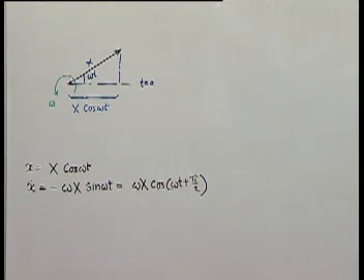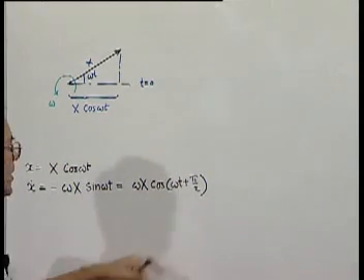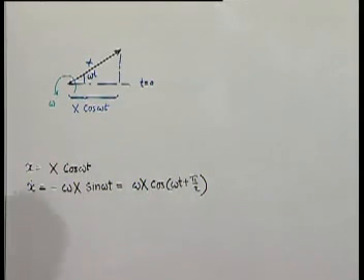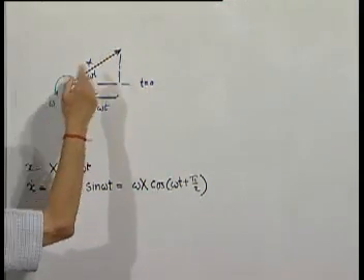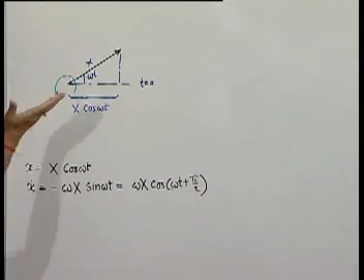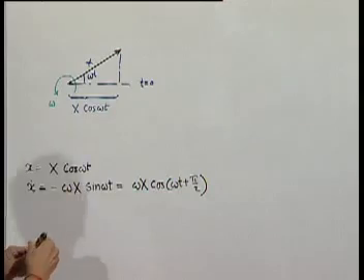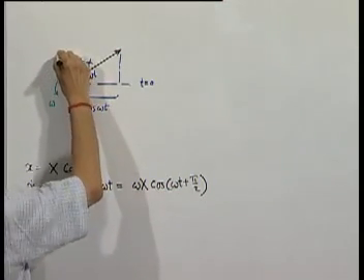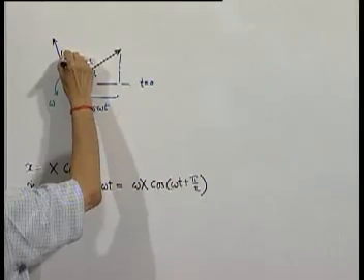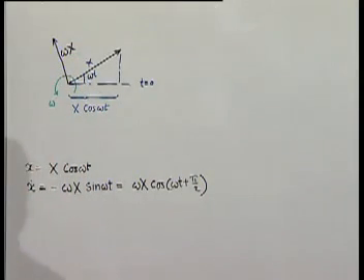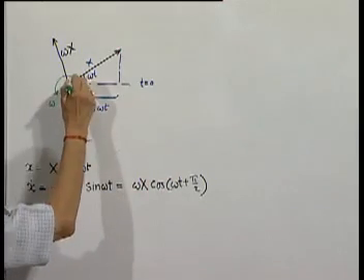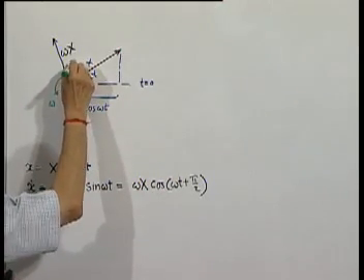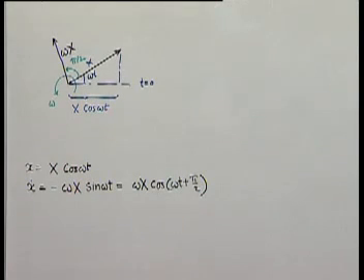So now it is again a harmonic function of time, whose magnitude is omega x, and it is leading the x vector, or the vector representing the position, by 90 degrees. So x dot will be represented by a vector whose length is omega x, leading the position vector by 90 degrees.